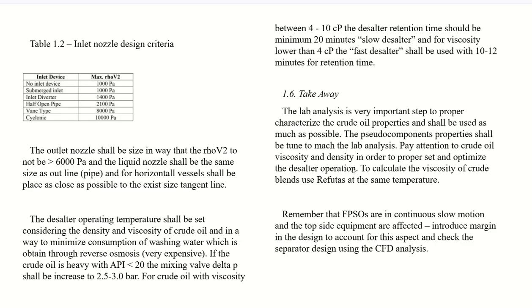To calculate the viscosity of crude oil, use refrigerants at the same temperature. I think this is a viscosity chart which nowadays is available through the lab. Remember that FPSOs are in continuous slow motion and the topside equipment is affected. Introduce margin in the design to account for this aspect and check the separator design using CFD analysis. They are saying that where three-phase separators are used, use CFD to see that the separation efficiency is met.